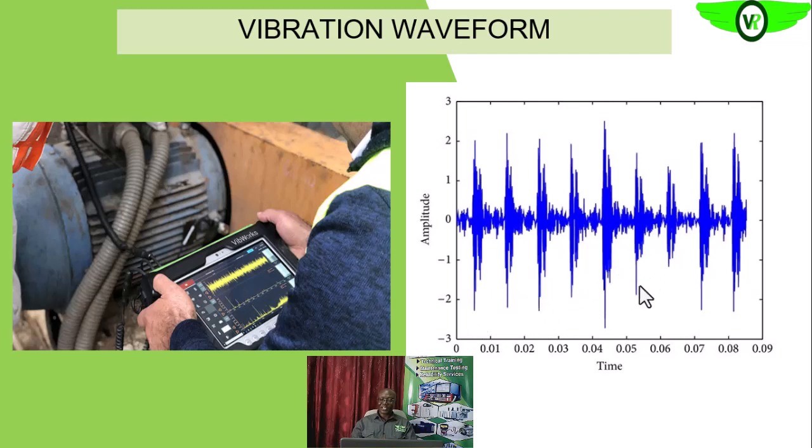Are you getting it? And this pattern, this increased vibration, if you also look critically, you will see that they are occurring at regular intervals. That will give you a sense that something is happening at these intervals. It could be in a pattern, especially if you look at these intervals coinciding with one-time RPM. Are we getting it? So that is the beauty.